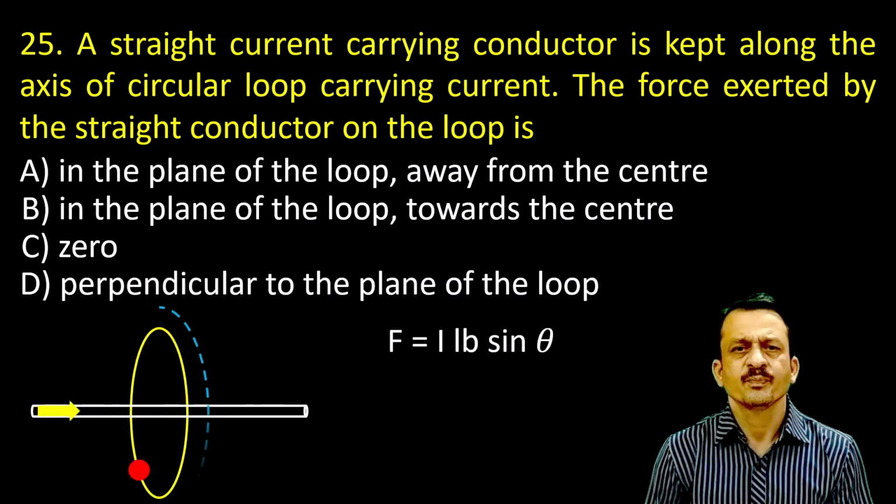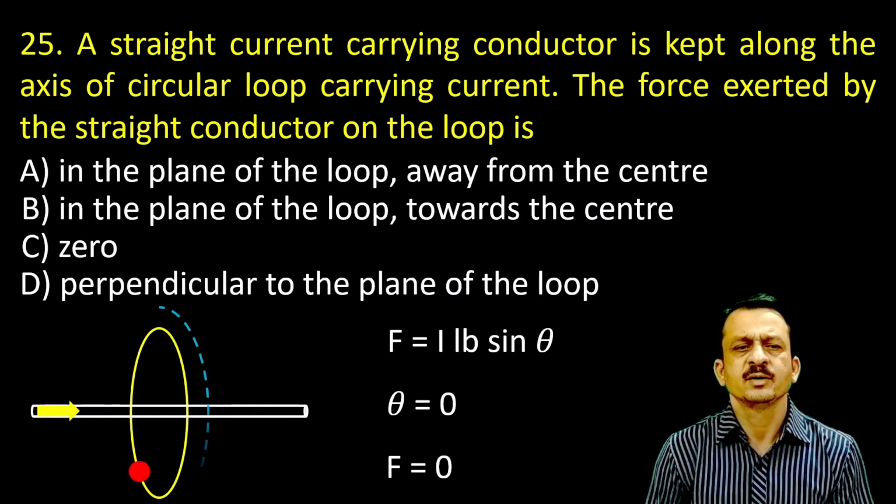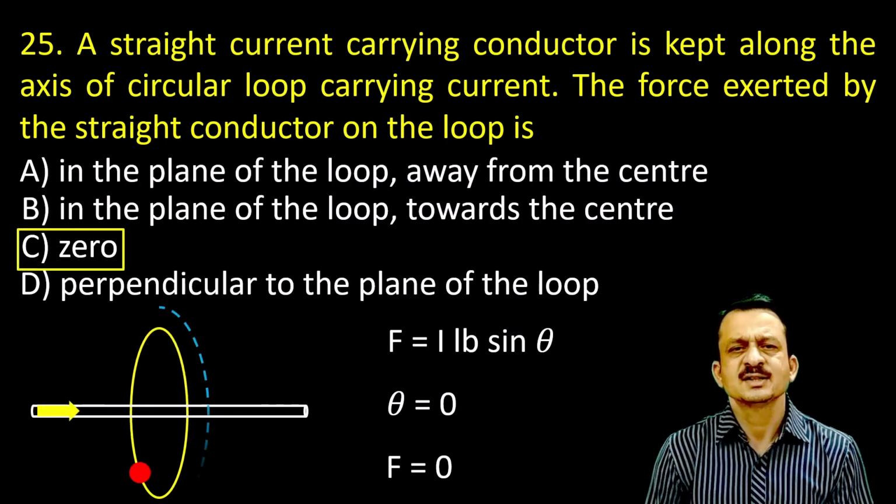Now, formula F is equal to I L B sin theta. Now, here theta is 0, therefore sin 0 is 0, and hence the force is 0. C is the right answer here. Move on to the next problem.